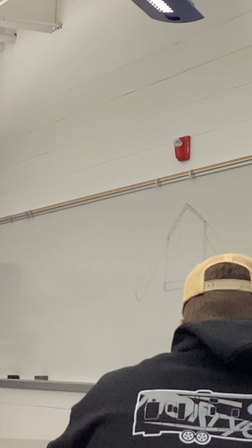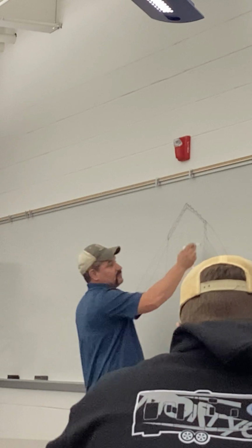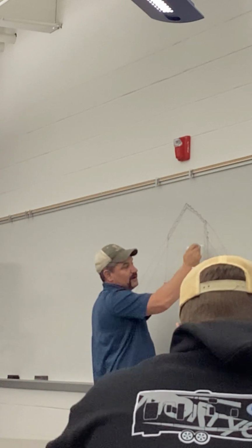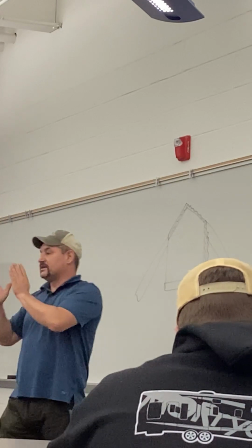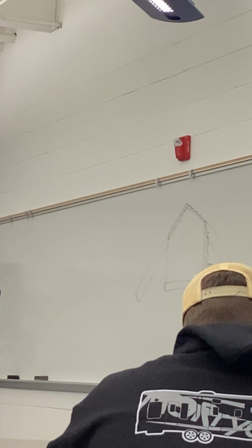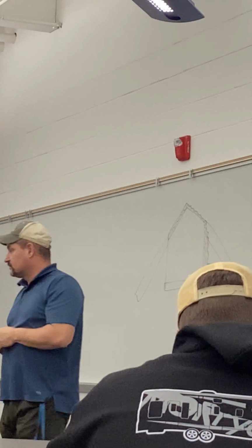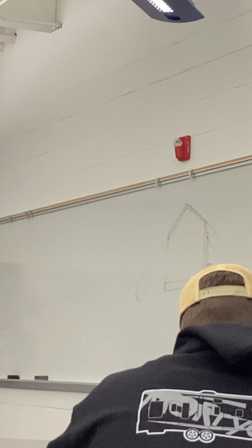So, what you should do is totally encapsulate it by going in here and either putting plastic or drywall or plywood on the backside so that it has drywall on both sides. If it has drywall on one side, it is not very effective. So, what does that mean for insulation in general? It's only as good as the person who installs it.